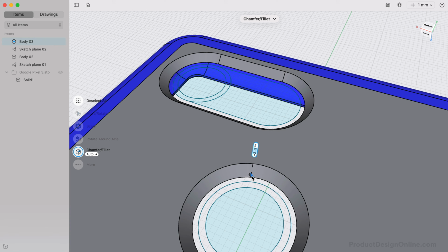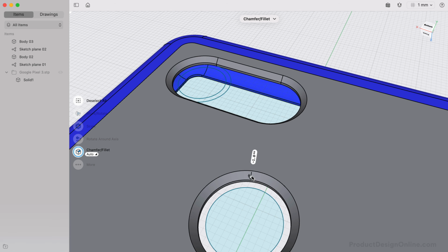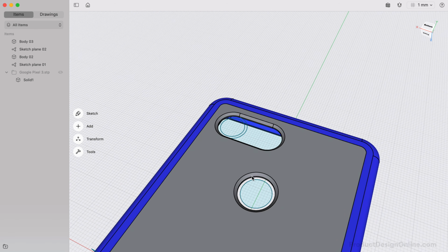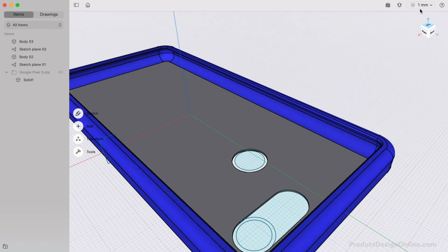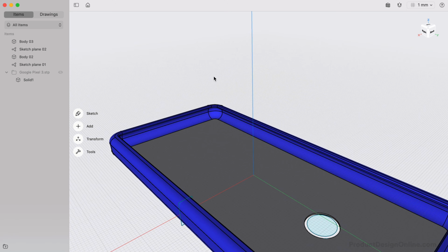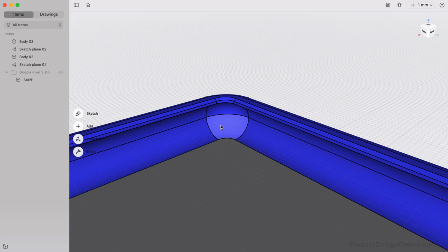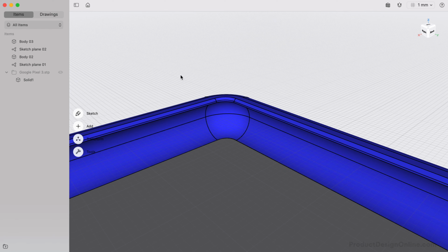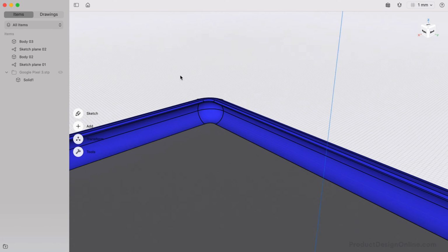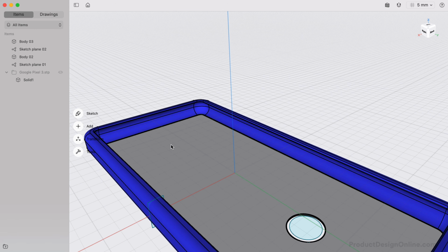If you plan to 3D print this, I also recommend adding a clearance of 0.5 mm. This, along with TPU filament, will provide enough flex in the final print to serve as a functional phone case. Select the 2 interfaces and type out -0.25 mm. This will offset the faces on each side, totaling our desired clearance of 0.5 mm. Keep in mind the bottom face is a separate 3D body, so you'll want to offset that 0.25 mm as well.